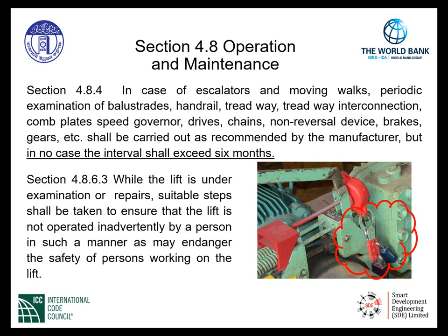Maintenance and operation is key with respect to these mechanical and electrical machines. They must be maintained and must be operated in accordance with the manufacturer's instructions specifically. Section 4.8.6.3 indicates that while the lift is under examination or repairs, suitable steps shall be taken to ensure that the lift is not operated inadvertently by a person in such a manner as may endanger the safety of persons working on the lift.